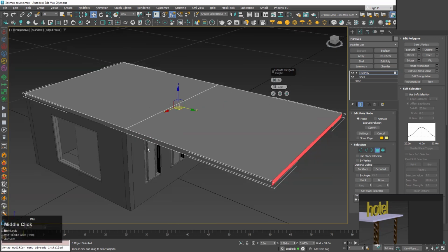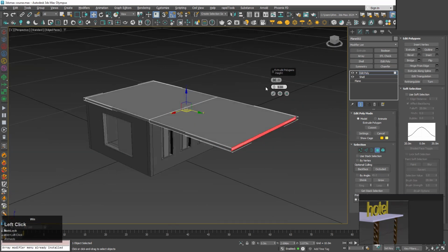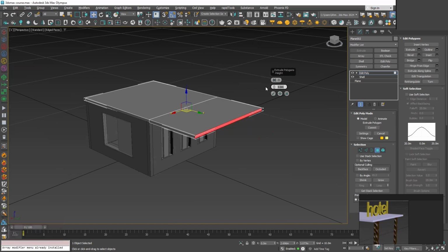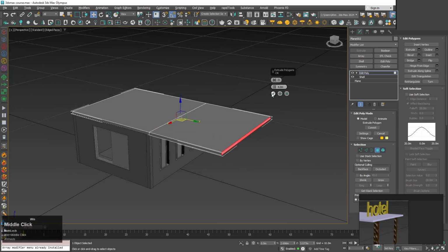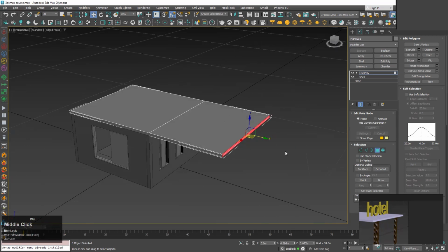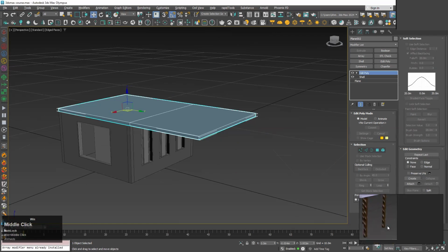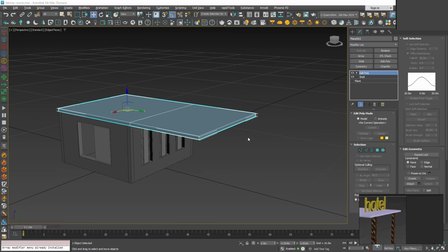You can see we now have that cantilever ceiling going on. So let's dial 3 meters. I think 3 or 4 meters may be enough. So let's click on the tick. This will give us a nice cantilever slab, or the nice cantilever ceiling that we have here. So now, before going to the columns, let's add a text that says hotel.